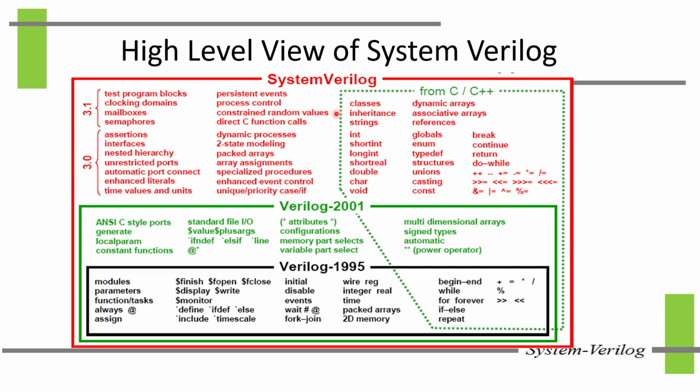After that, in 2004 or 2005, we had the System Verilog specification. Some of the EDA vendors had already started supporting these constructs by the time the formal LRM was out. It was basically an extension to Verilog, and it supports a lot of new features: we have classes, we have inheritance, we have program blocks, we have clocking domains, we have assertions, and many more features.